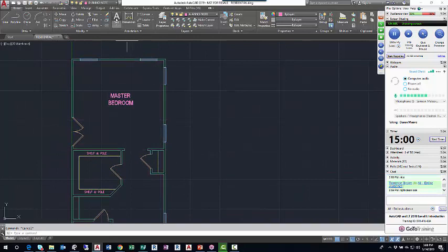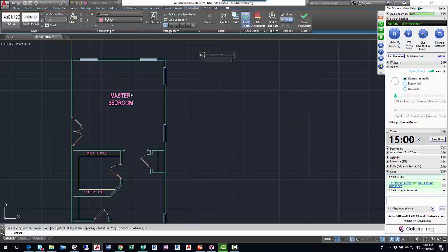I'm going to click multi-line text, and I'll make a little window to hold my text off to the right. And so you've got a style panel that allows you to change your text style. If I didn't want to use notes, I could change that now. I could actually change the height if I want to. I could match properties with my text. If I had text that was not the right height, I could match properties. Change the font, change what color it uses, change justification.